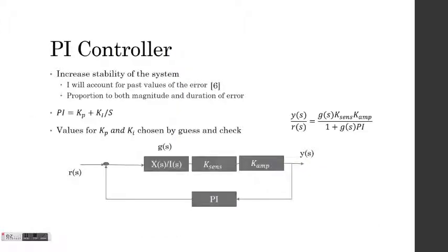The PI controller is a combination of proportional and integral. The contribution from the integral term is proportional to both the magnitude of the error and the duration of the error. The I value will account for past values in error. The integral term accelerates the movement of the process towards the set point and eliminates the residual steady-state error that occurs with a pure proportional controller. However, since the integral term responds to accumulated errors in the past, it can cause the present value to overshoot the set point.